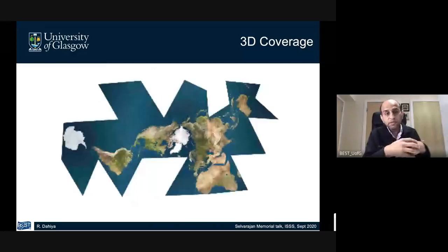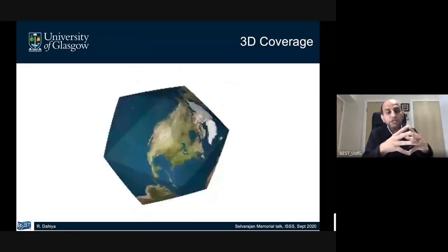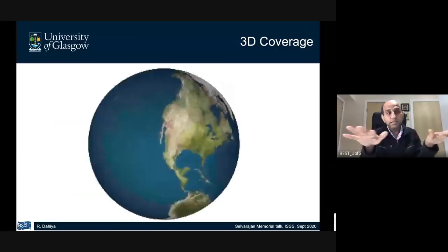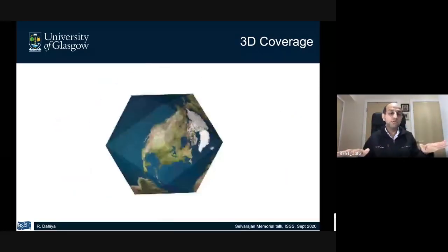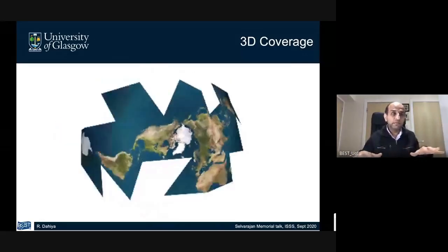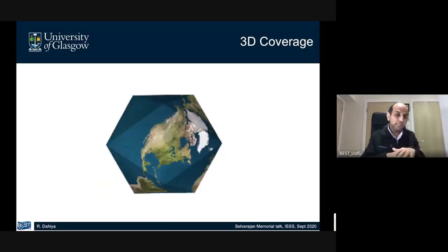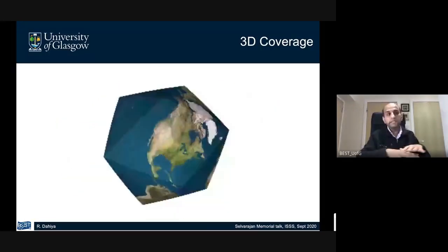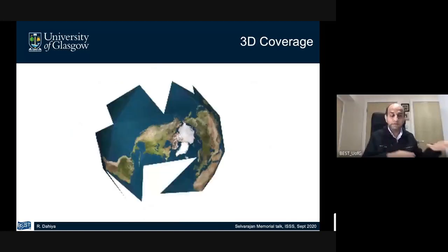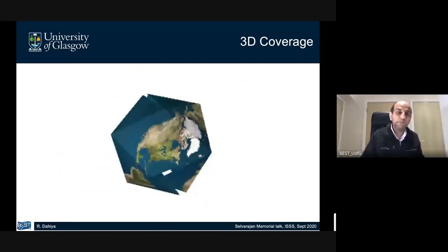Essentially, if you look at a spherical surface, you take triangular projections. From those triangular projections, you can make a 2D layout. And once you have the 2D layout, you know how optimally you can cover this surface with the skin. And if the skin is also made of triangles, the maximum coverage is possible. That's why we developed the skin with triangular patches.